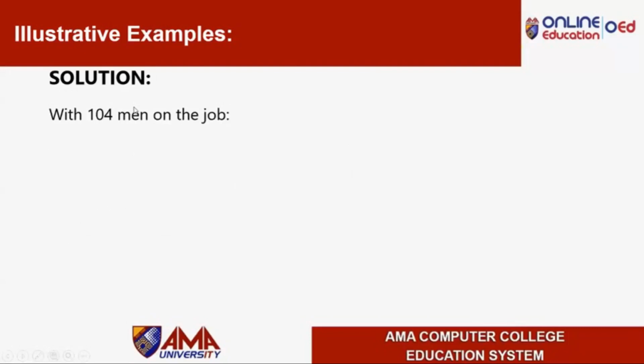Now let's compute with 104 men on the job. So where did we get this 104? Of course, from the previous, diba, we computed the additional. How many men do we need to complete the 100 days? Based on the computation, we need an additional 24. So 80 men, which is the existing, plus the additional 24 will be 104 men. So now, let's base on the 104 men.